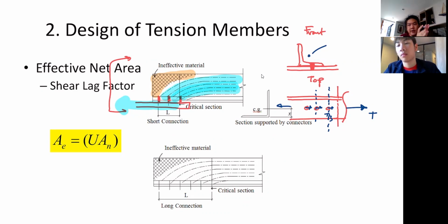It can never occur in the second line, because if you talk about the second line, it means that you already have 1/3 of the force traveling down the first bolt. So we are always going to have the failure at the critical section at the first bolt. Any question on this one? Are we crystal clear then?